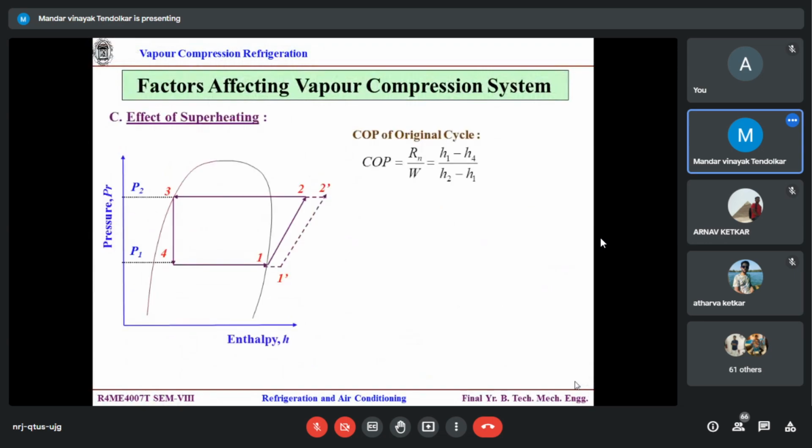Yes, sir. So this is the reason. If you start, this is my saturated liquid, and here is saturated vapor, written here, see. So the moment you start going out of this, towards the more and more superheated part, the slope of this isentropic compression is getting flattened. And a flat slope means more work. Do you agree? Now let us go back to this slide.